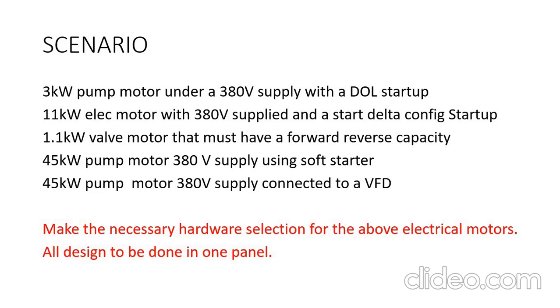For example, you can have a direct online startup and that is all they'll have, or you can have a VFD setup and that is all they have. So with this hardware, we have to make the necessary switchgear selection for the above electrical motors, and all design is going to be done in one electrical panel or one electrical cabinet.